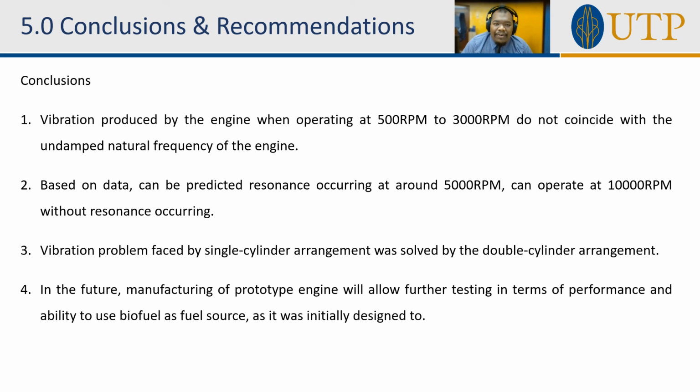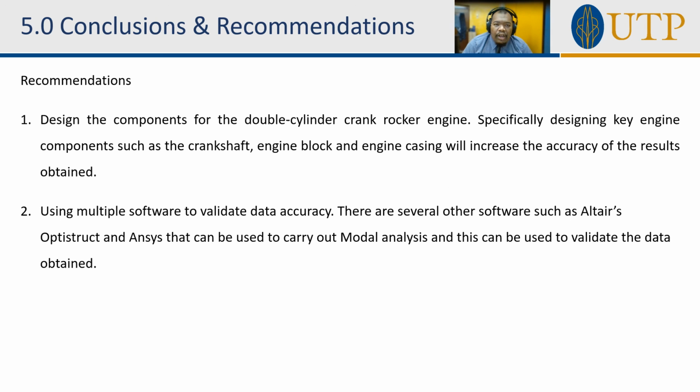The double-cylinder crank rocker engine managed to solve the vibration problem faced by the single-cylinder engine, and in the future the engine prototype can be manufactured and further testing such as using biofuel as the fuel source can be carried out. For future works, the components for the double-cylinder engine such as the crankshaft, the engine block, and the engine casings must be designed since it will increase the accuracy of the results instead of using the single-cylinder parts. Using multiple engineering software such as Altair OptiStruct and ANSYS to carry out the model analysis will also cross-validate the results and improve accuracy further.